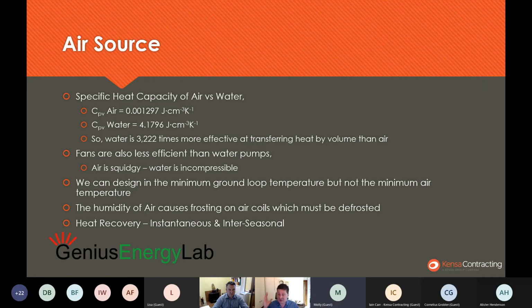But ultimately that does take energy and it reduces efficiency. So for our climate, air source is quite significantly an inferior technology to ground source in terms of efficiency. Of course, the cost is different, and then the cost of installation is different because there's no ground loop to go in. Bottom line is an air source heat pump box for box against ground source may be slightly more expensive because it's an item that's built to sit outside.